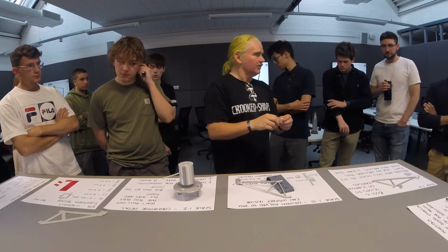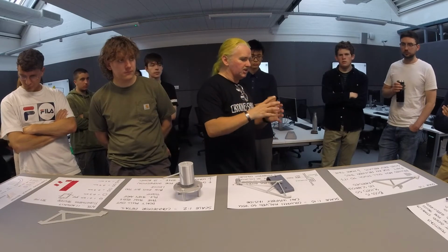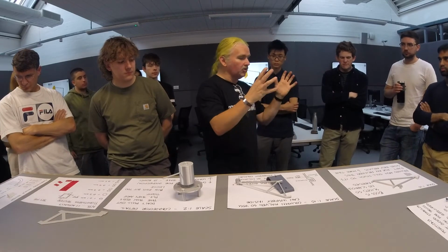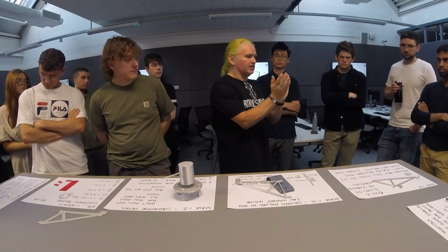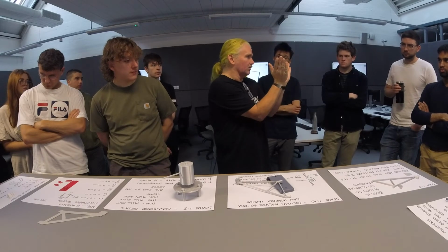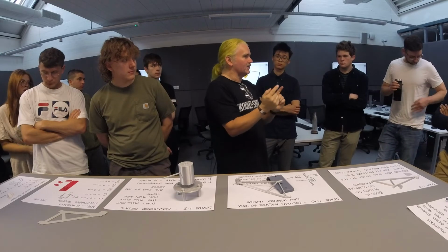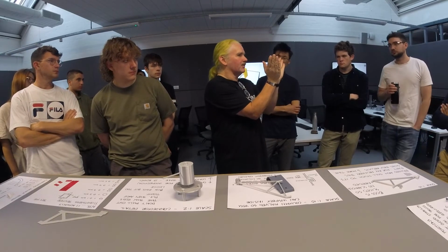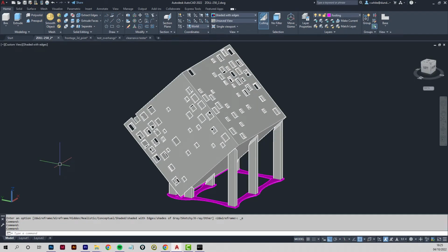Yeah, absolutely. One of the models we got for first years is a building in Essen. It's just a concrete box with loads of holes in for windows. Really random looking thing. And to get it to print, I had to tilt the whole model at 45 degrees. And what I hadn't got is enough support. I hadn't put any support outside. It started to fail, and I was like, what's happening? I didn't realise the whole thing was just tipping over. So I had to intervene on that one.